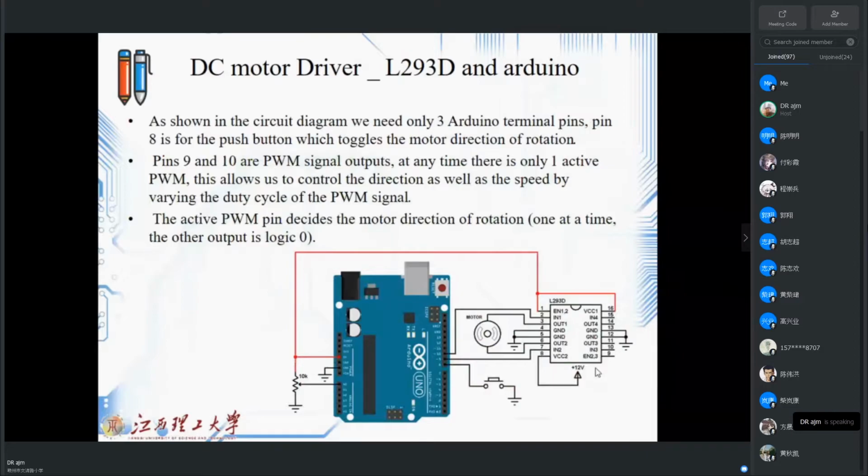Now we should connect it to the Arduino. As we said here, we just need two pins, IN1 and IN2, if I want to run the driver. Two pins are enough for me. I made one a little bit more complicated design here, in which I'm going to generate the PWM on pins number 9 and 10, and then they give various speeds of my controller.